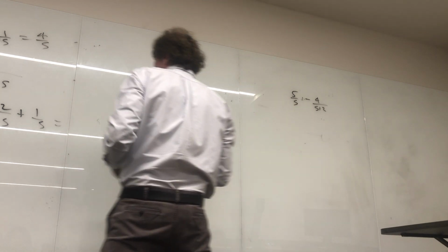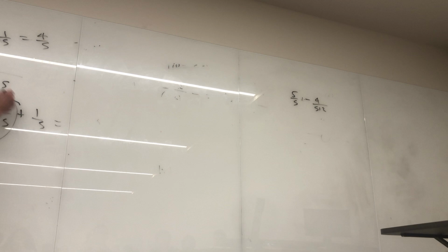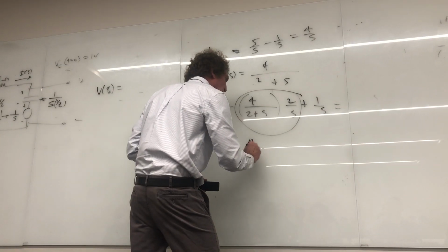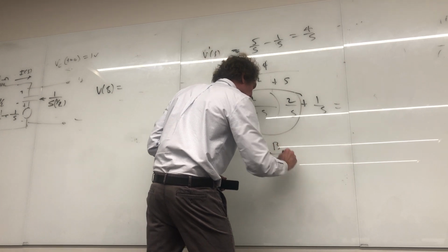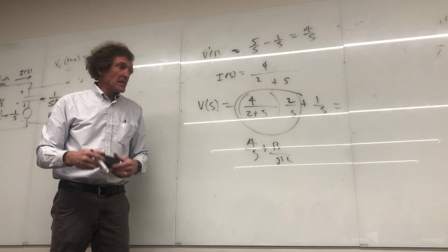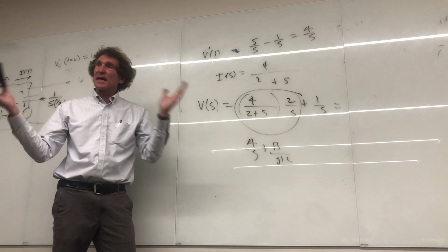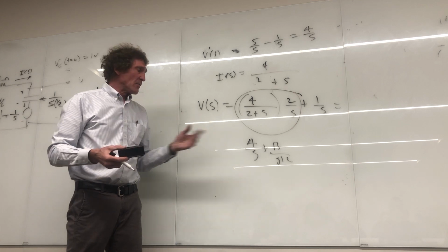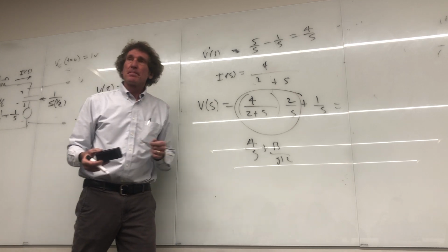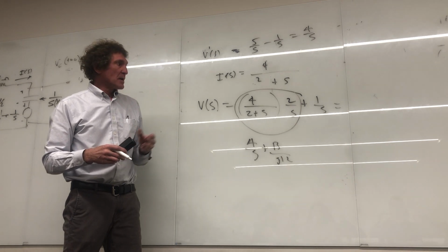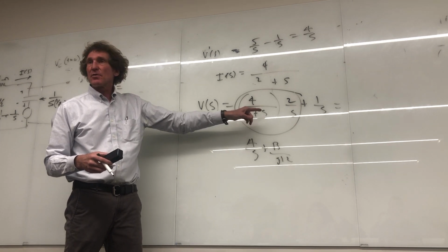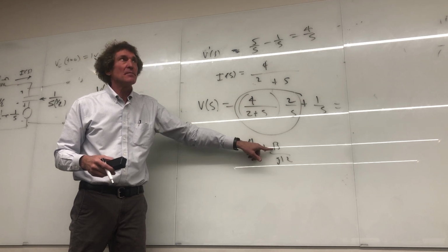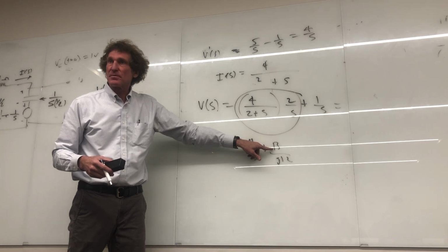All right, here's what I did. I took these two and I did a partial fraction expansion. If I do a partial fraction expansion, the poles are a over s plus b over s plus 2. Then I figured out what a and b were. And then once I did that, I saw I have a 1 over s, I added those 2 terms. Understand? And it became 5 over s. So where did the minus come from for b then? Because when you do the partial fraction expansion, the second term is minus 4 over s plus 2.